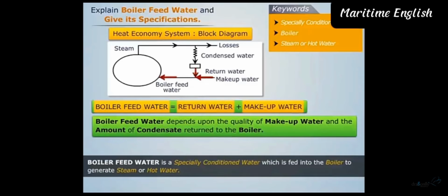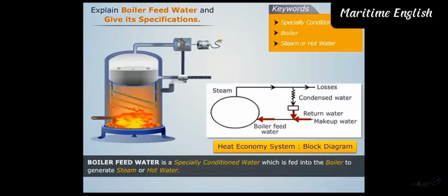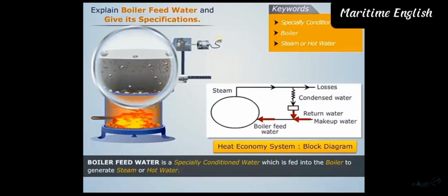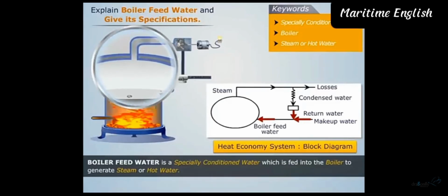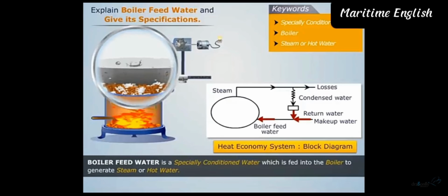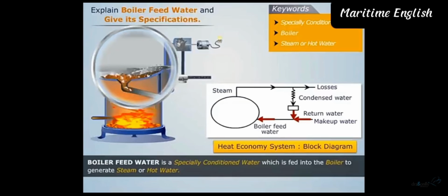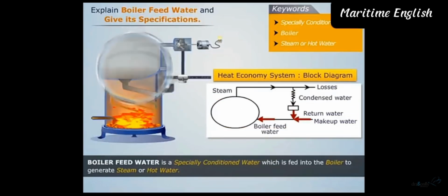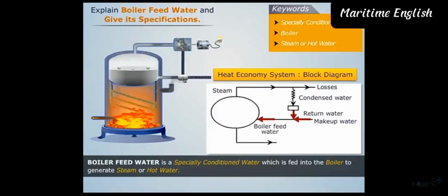the boiler. Sometimes we see that some impurities settle down at the bottom of the boiler after the steam is produced. We know that steam which escapes from the boiler normally contains liquid droplets and gases, so the remaining water at the bottom of the boiler might pick up all the foreign matter from the water that was converted to steam. This results in the accumulation of impurities at the bottom of the boiler. These impurities can be removed by discharging some water from the boiler to the drain. Such a process of blowing the impurities from the boiler to drain is called blow-down operation.